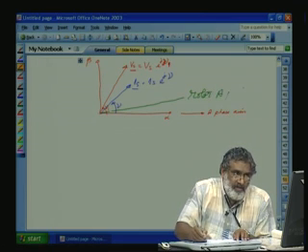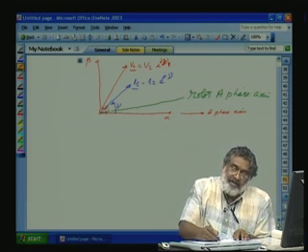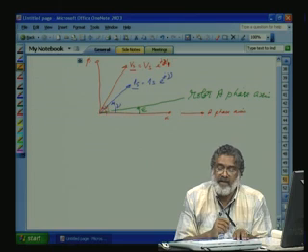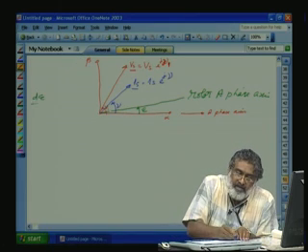Rotor A phase axis. So, this is moving with an angle sigma. Sigma is also a function of t. What is d sigma by dt? No, d epsilon by dt. d epsilon by dt is equal to omega r, the rotor speed.